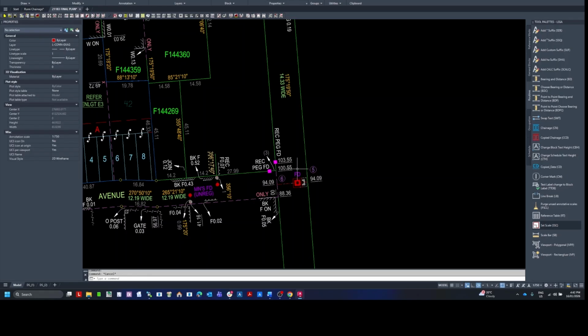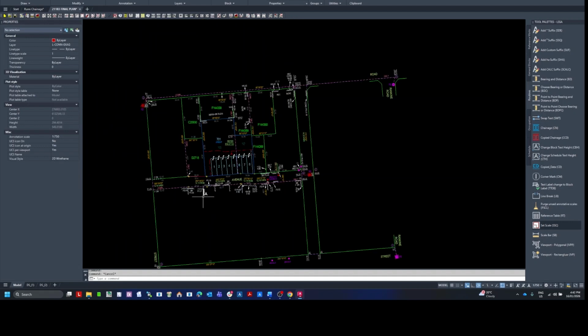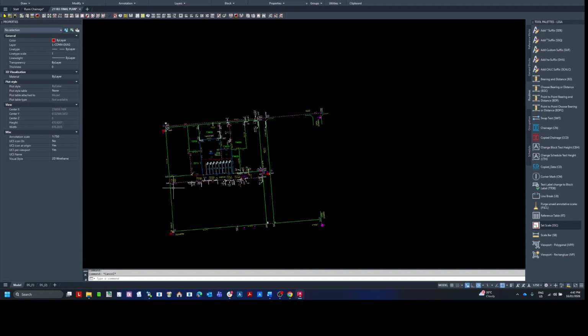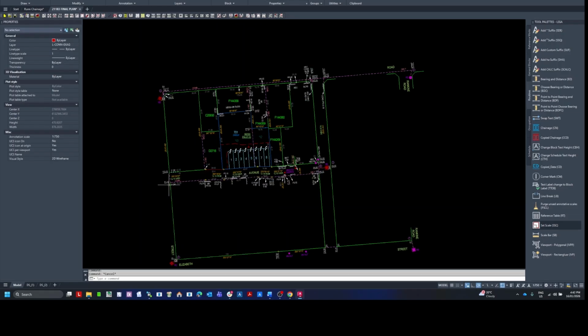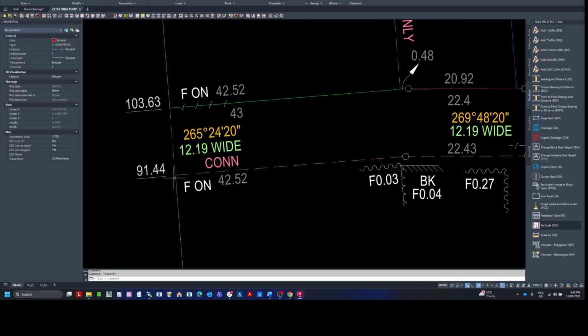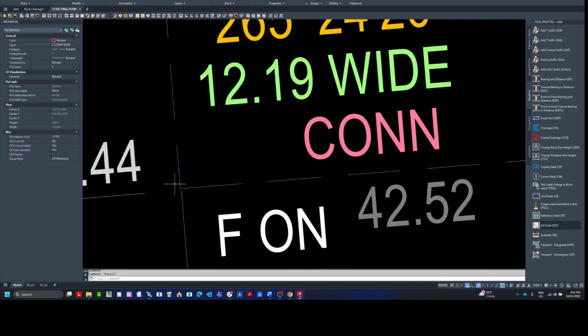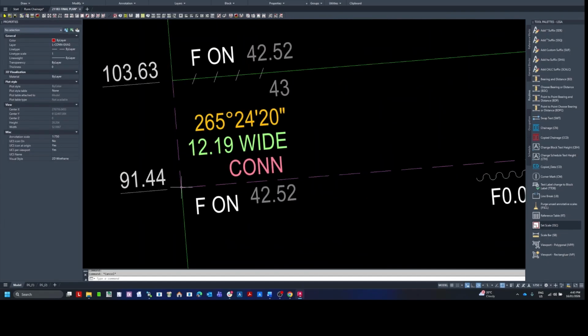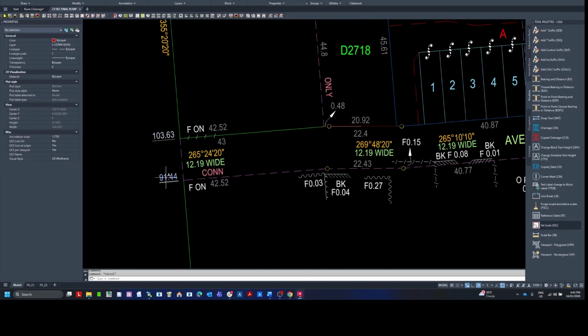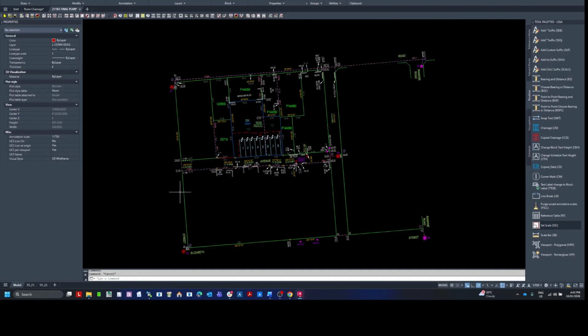Another important factor is to check that abuttal lines are snapped to connection lines and parcel boundaries along chainage runs. We do find that sometimes the extract files are used, and this can cause a slight mismatch between a connection line and an abuttal line, and any break within the line could be enough to cause this chainage run to not be able to be validated along the full run.